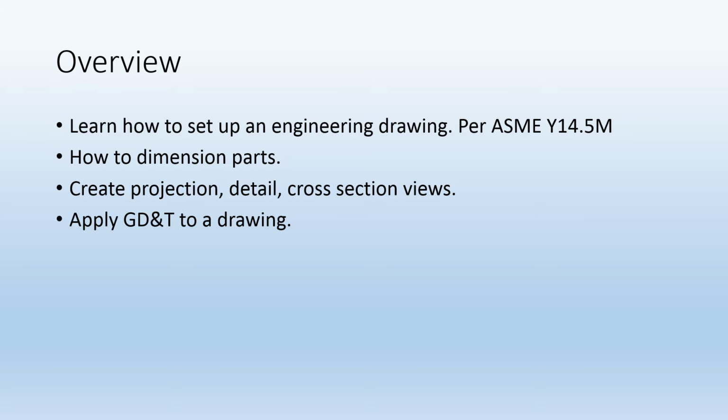Now, there's a little bit of trouble with this system because even though you apply a plus minus 5, meaning it can move to the left 5, but you can also move up 5 from there. So you can imagine if you were to actually measure the distance, if you went left 5 and up 5, you would have to do the triangle. It's a 45, 90 triangle. So you have to do 5 squared plus 5 squared, take the root. So you'd actually find it's a larger value than what you're expecting in terms of your distance from your ideal point.